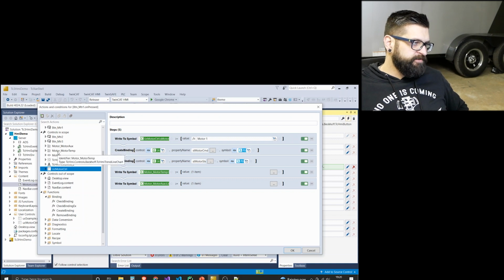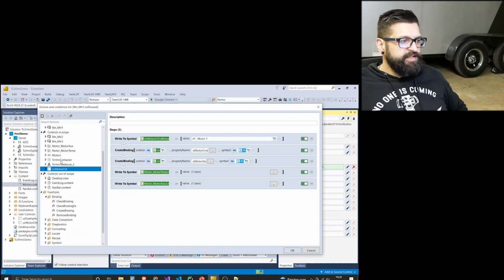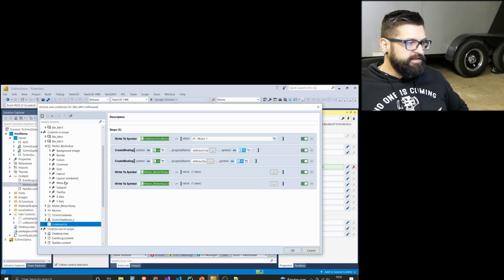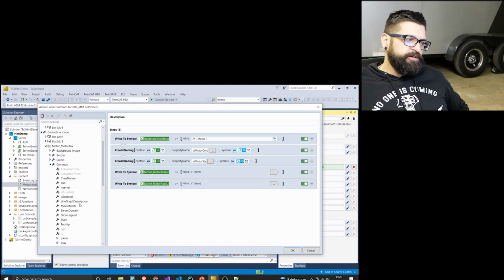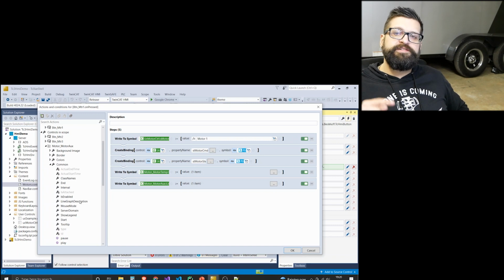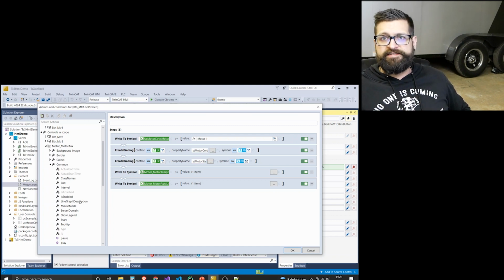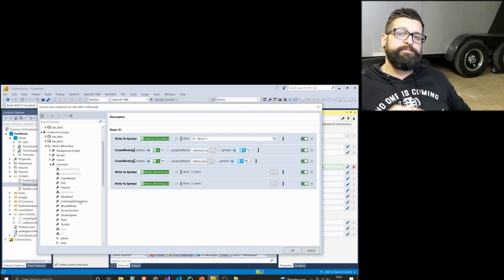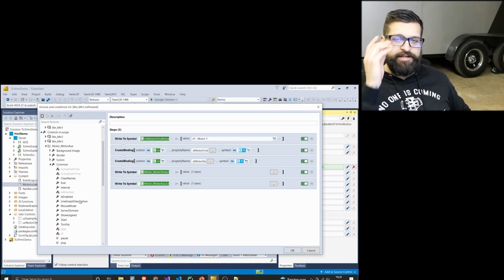Well, actually, correction. You drill down in first, and you find out what you need to act on, the property you need to act on. The property that I need to act on is the common and line graph description. In the trend line chart, the line graph description is the definition of the symbol or symbols that you want to display, that you want to track. There are different properties, configurations for your y-axis and your x-axis, but when you're actually passing in symbols to trend, you do that with the line graph description.